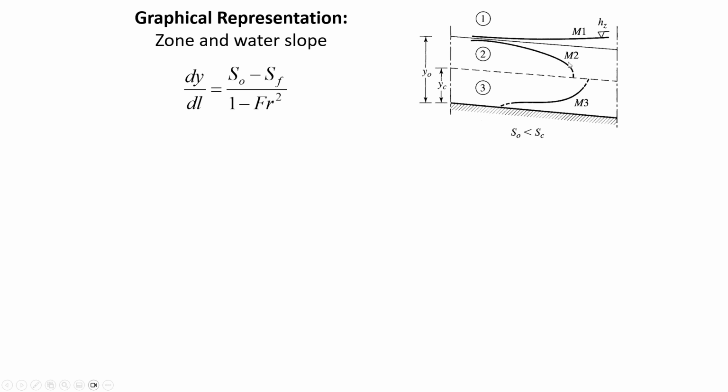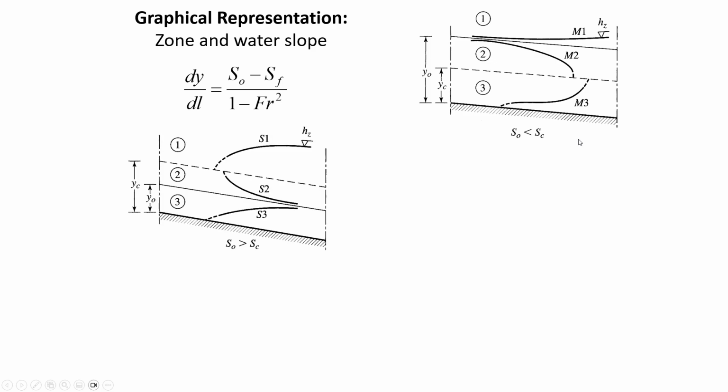So what would cause an M2 profile? It could be that downstream the slope gets steeper. And so there's some sort of a, not even necessarily a drop off, it's just maybe downstream the slope is steeper, and so you've got a certain water depth that's approaching a lower water depth. And M3 could be caused by an underflow gate.